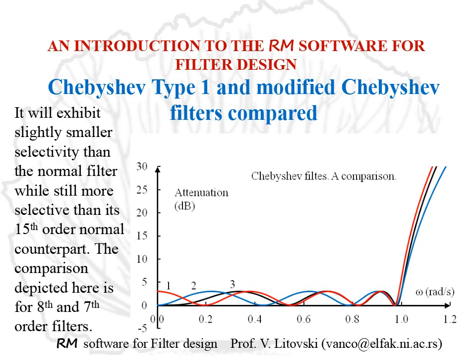As can be seen, number 2 and number 3 are starting from the origin, while number 3 has its attenuation in the stopband very similar to the one of number 1. So practically the difference between the red and the black line is the loss which is to be paid for the advantage of having equal resistors.